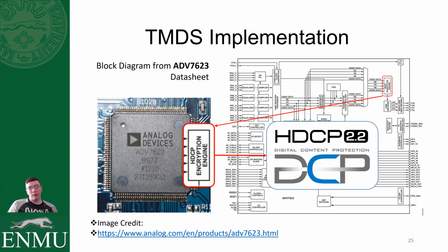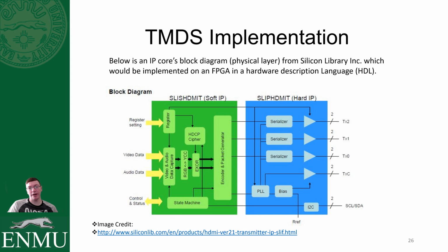So you would not be able to make a device that is fully compatible with all the frame rates, resolutions, and things like HDR that come on modern delivery formats, like those HDR Blu-rays and 4K content delivery. So you couldn't do it by yourself. You would probably have to be somewhere in the industry, or at least become an HDMI adopter if you're a sole proprietorship or something like that. But I would be remiss without mentioning HDCP if I'm talking about HDMI.